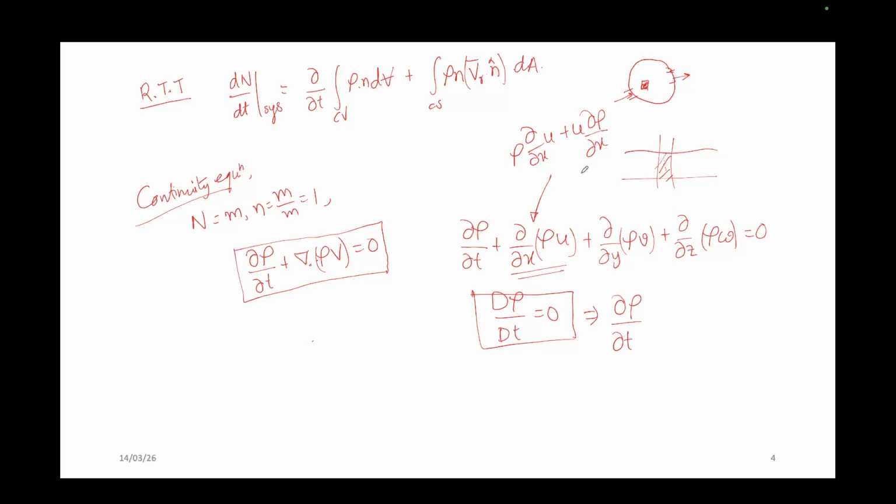So if it is a compressible, sorry, if it is an incompressible fluid, in that case you can eliminate some terms. Which term can you eliminate? Can anyone tell? If it is an incompressible fluid, which term can you eliminate? Anyone? So if it is incompressible, then you can eliminate this term because it's the rate of change of density. So there should be no change in density, right? So that's why I'm writing this in a different way for your understanding.